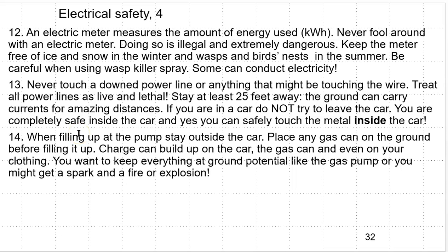Never touch a downed power line or anything that might be touching the wire. Treat all power lines as live and lethal. Stay at least 25 feet away. The ground can carry currents for amazing distances. If you're in a car, do not try to leave the car. You're completely safe inside the car, and yes, you can safely touch the metal inside the car.